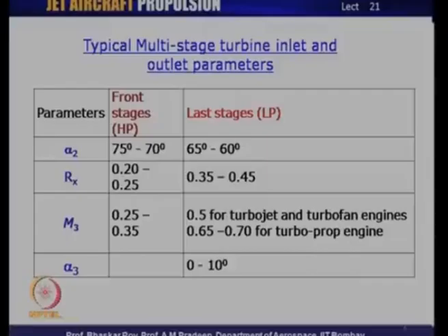You simply want the flow to go out with maybe a very small amount of thrust creation. So, more of the work is being done through the propeller, whereas in turbojet and turbofan, the typical full jet engines, you still have a nozzle as another component of the engine, and that nozzle is going to create higher acceleration and a high velocity jet for thrust creation.